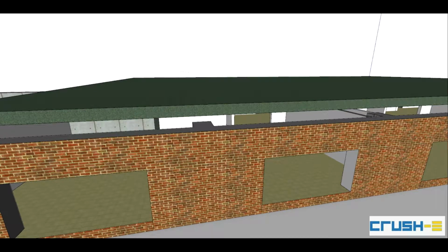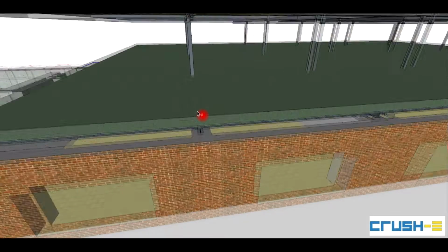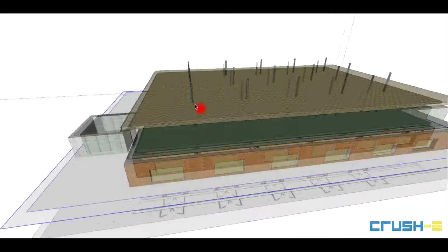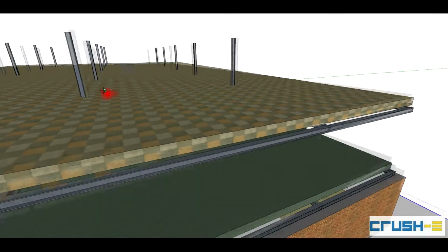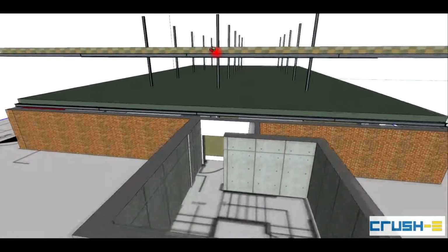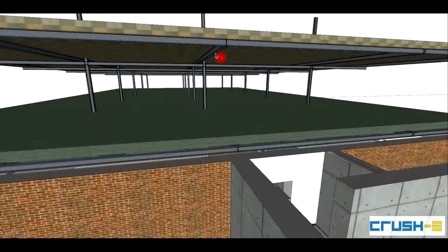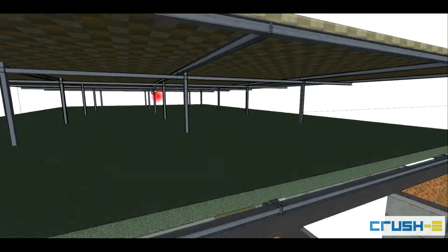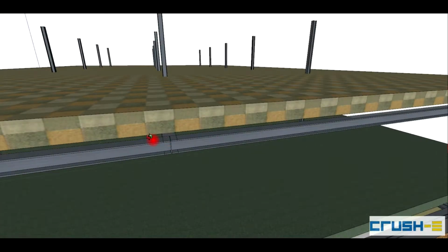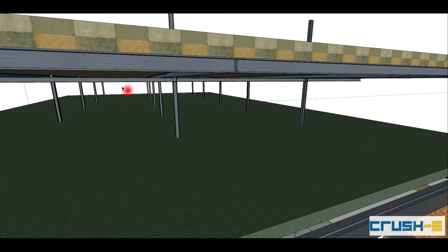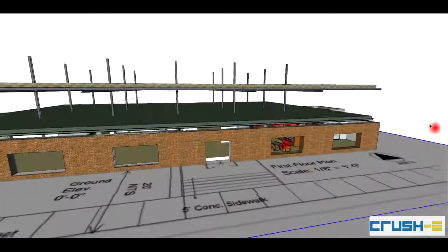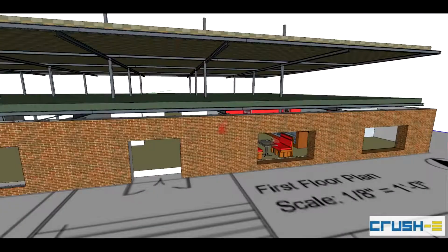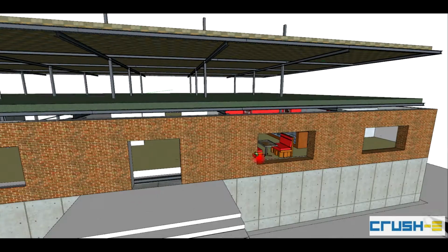We actually have a girder and truss system installed on this particular model. There you go. And it shows pretty much the grid outline of everything. So those are all the columns. There's girts underneath. I can actually put in bridge joists, or bar joists, or whatever needs to happen underneath, purlins, whatever. Get very detailed, but it makes a huge model. So try not to do that if we don't have to.